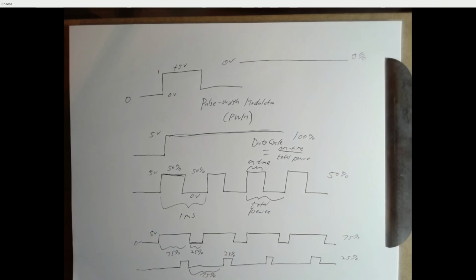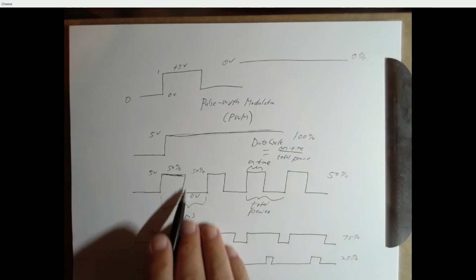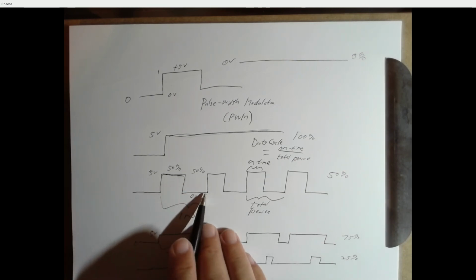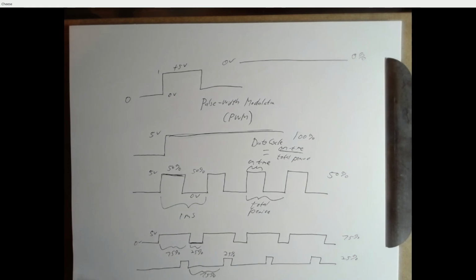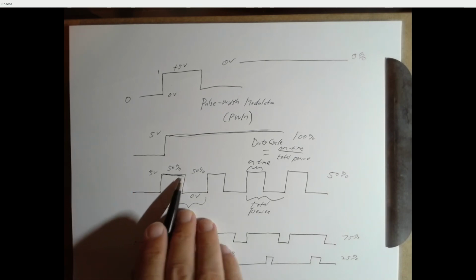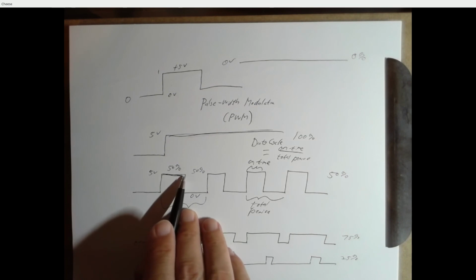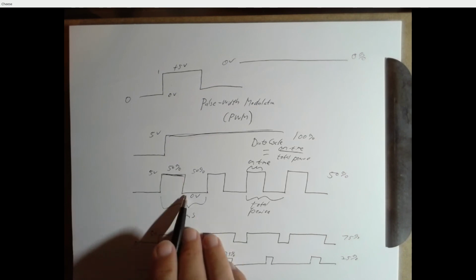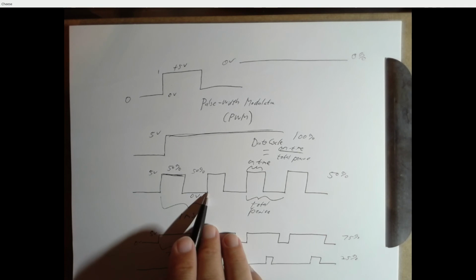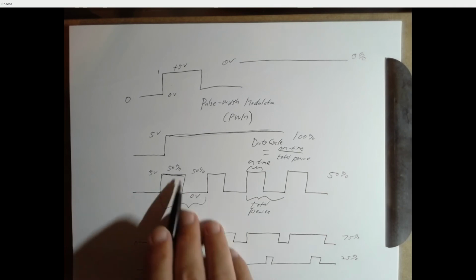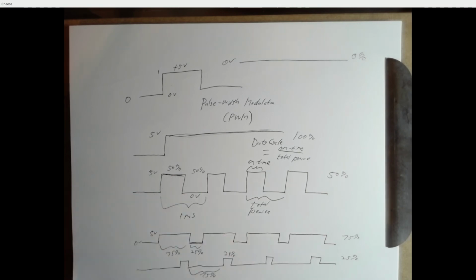So pulse width modulation is a generally useful technique, and we can do this with what we already know on a PIC processor. We know how to turn on a bit in latch A, we could say bit set, and we know how to turn it off, we could say bit clear. And we have access to timers. We can do timing loops, or we can set up the timing subsystems, and we could say, hey, let's wait for half a millisecond and then generate an interrupt, and wait another millisecond, generate an interrupt, and each time we get an interrupt, let's just toggle the output value.